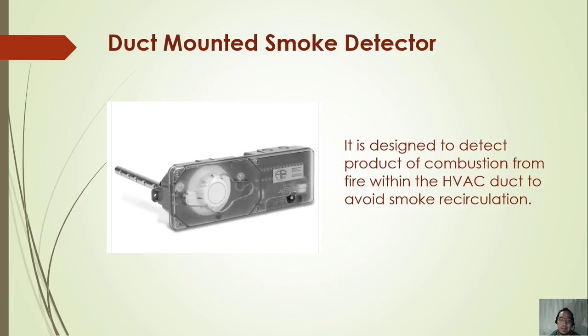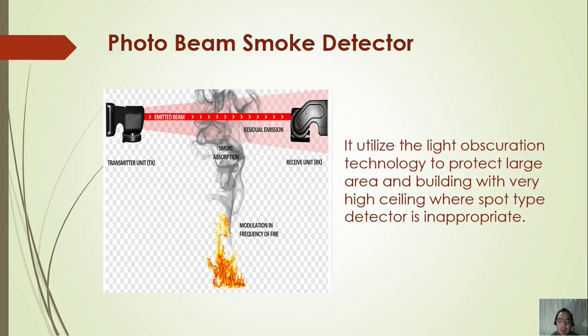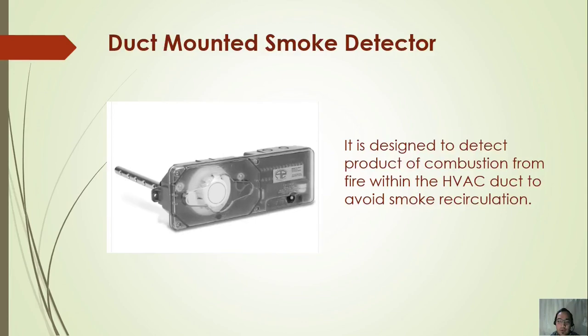So once we have a duct detector, take care guys, make sure that you are using a listed smoke detector for duct application. Okay?